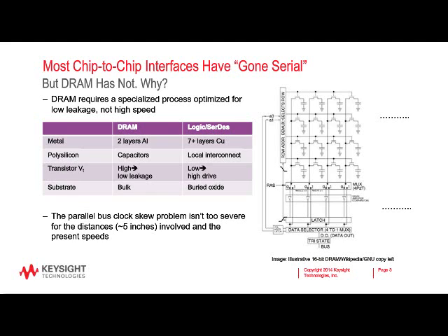The ones and zeros in DRAM are stored on very small capacitors, around tens of femtofarads, and the difference in charge between a 1 and a 0 is only about 100,000 electrons, so low leakage is absolutely crucial. As you can see from the table, the DRAM process is optimized for low leakage, but not the conflicting goal of a high-speed logic process for SerDes.